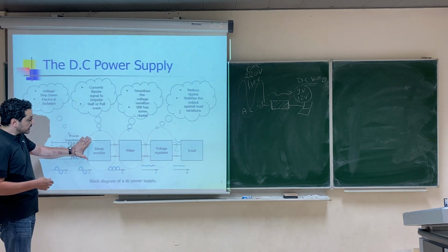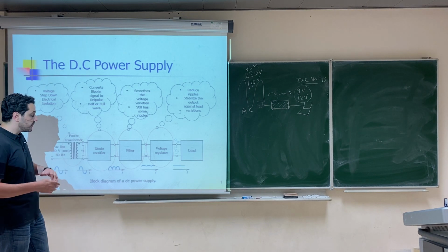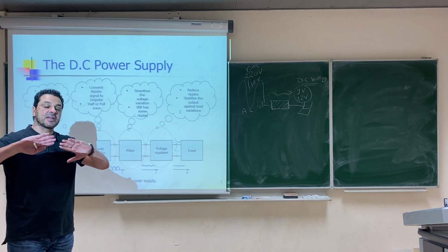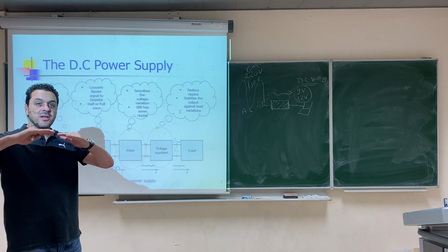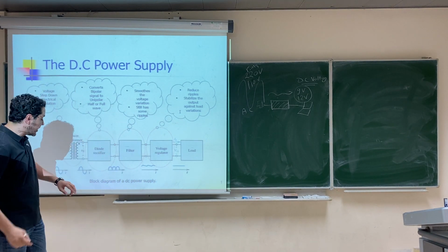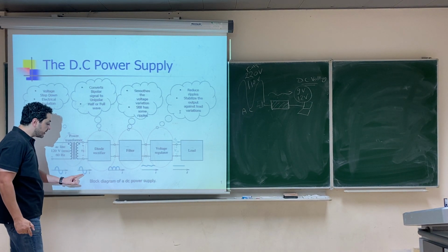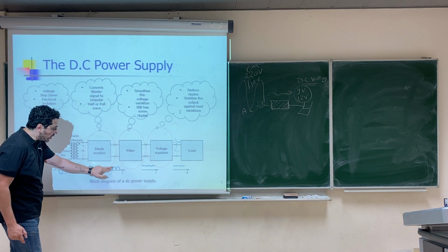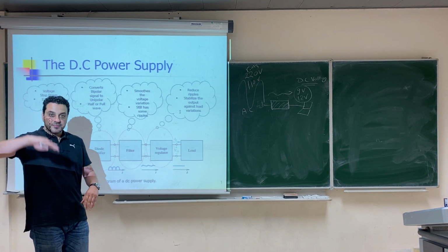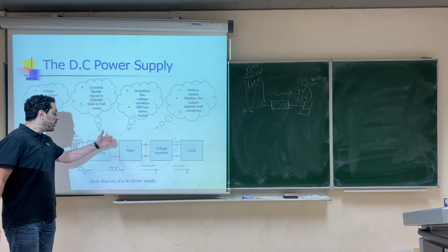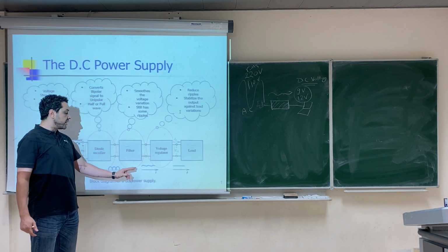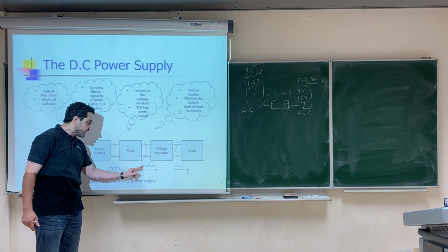And then we use a circuit called a rectifier. As we talked about before, the rectifier makes all the voltage positive. After the rectifier, the sinusoidal wave is converted to an all-positive signal like this. Then, in order to smooth down the fluctuations, we use a filter. After the filter, it smoothes down the variations in the voltage, so it gives you something like this.